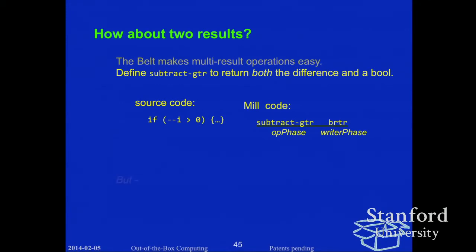Everybody's happy. Except you wind up with a huge opcode explosion because for everything that might produce a condition code-like result, you now have to have flavors that produce each of the individual possible conditions, and your opcode space, the bit space in your encoding, winds up getting rather nastily cluttered with stuff like that.